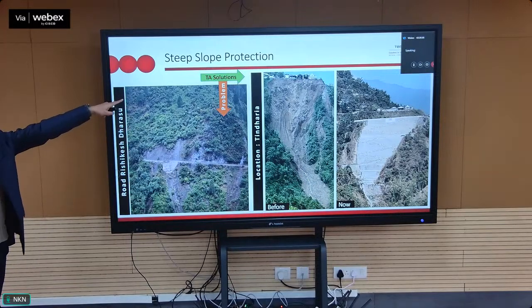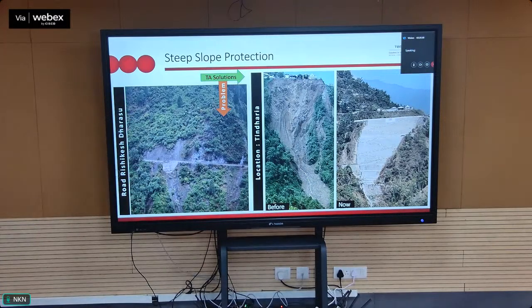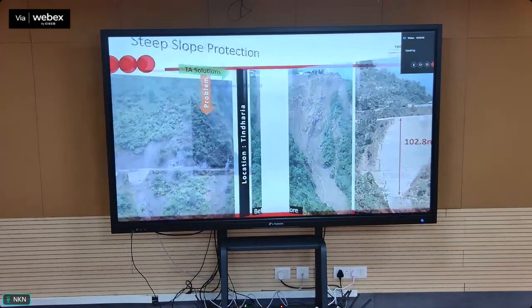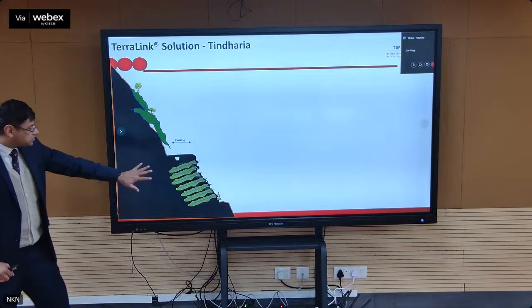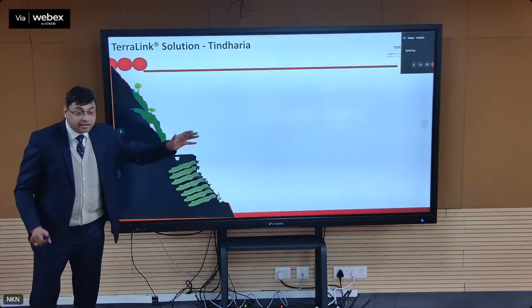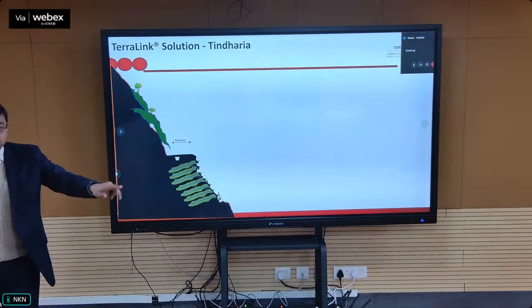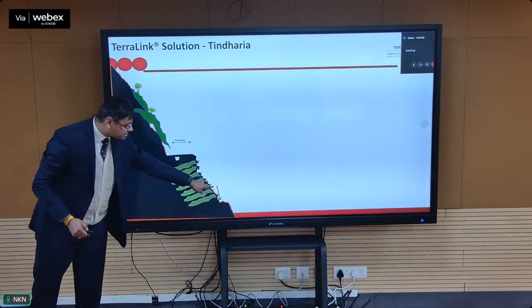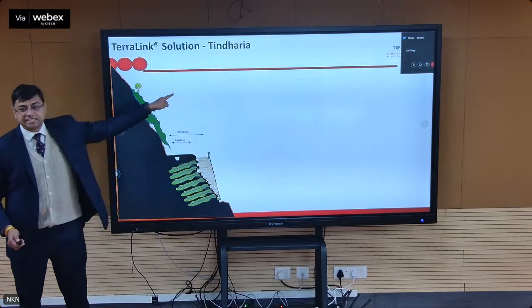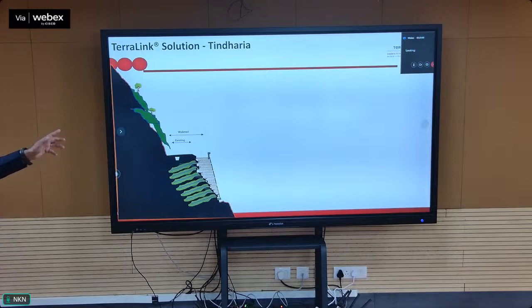The height of the slope is almost 150 meters. We build a wall. How do we build a wall that tall with such a small width? Simple combination of techniques. Use the existing face, reinforce that face with nails. From that face, we take out straps. From those straps, we build up a false fascia. Use the existing place to build up a bigger space.